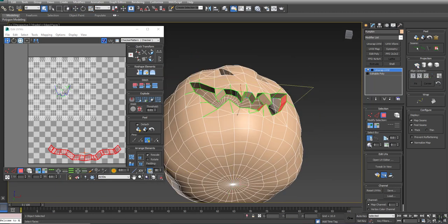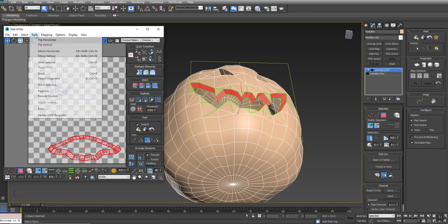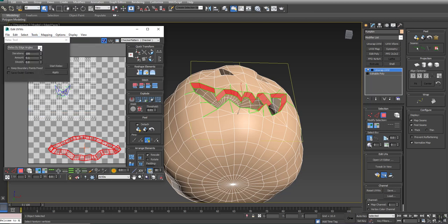Turn off the peel. Keep in mind, different versions of the software, the projections may look a little bit different, so don't worry too much about that, okay? I'm going to expand my selection out to my seams, and I'm just going to have to projection map that again. There we go. And I could just take these guys and relax them. Tools, relax by polygon.